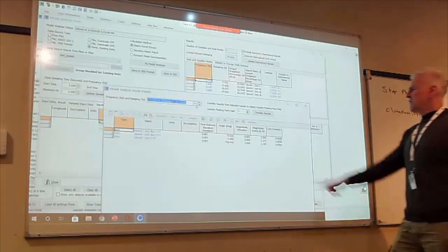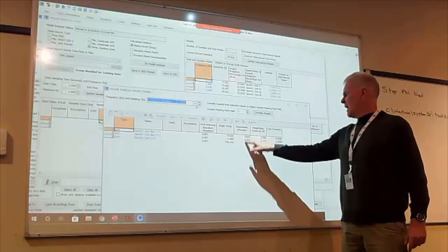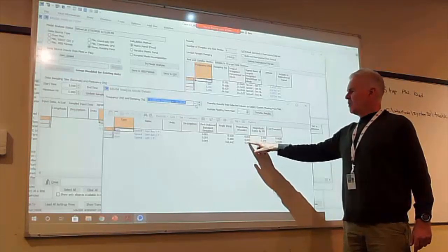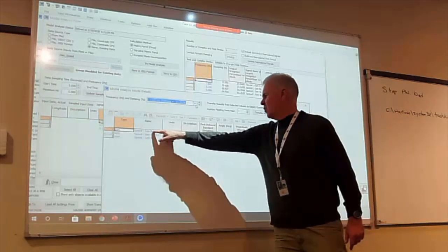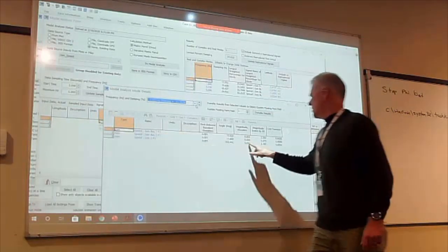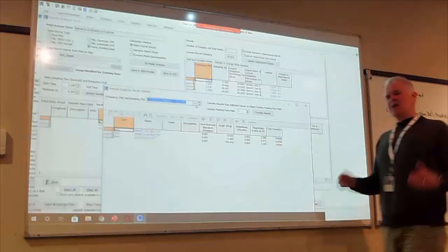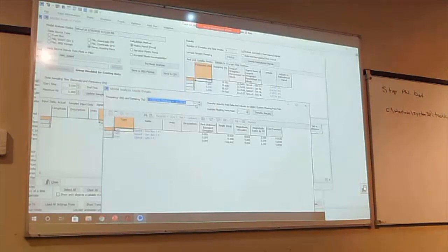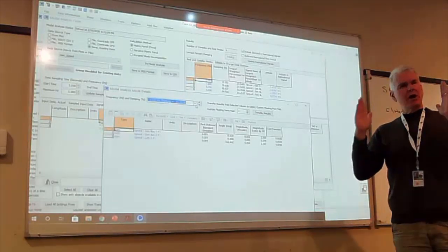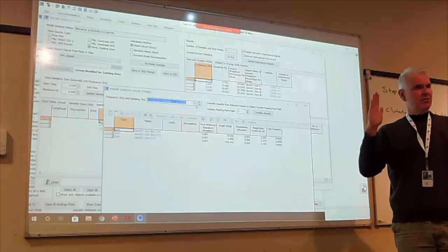Some of these values will be high, some will be low. What this is saying is that signal 1 and 3 were manifested in that mode, whereas 2 was not. So the way to interpret this mode is to say this 2 Hertz mode is generator 1 oscillating against generator 3.